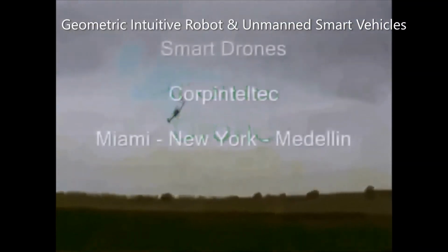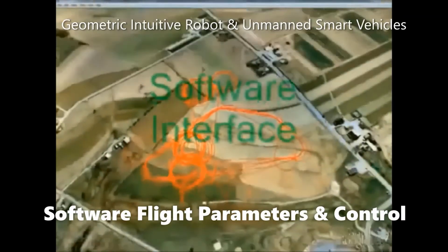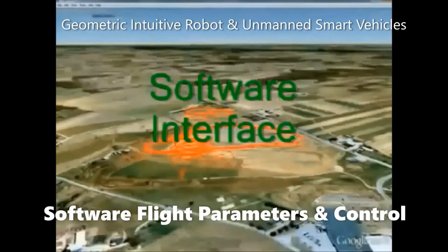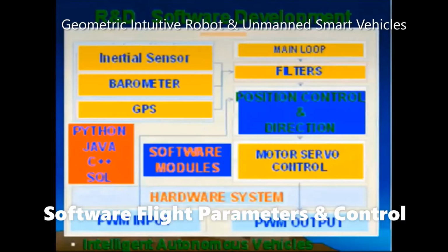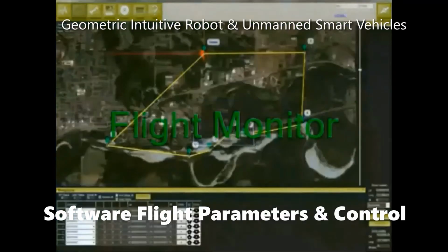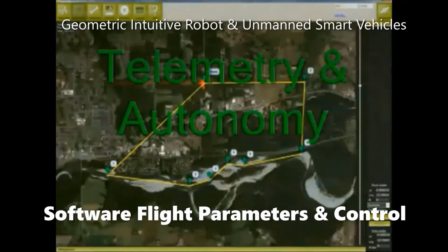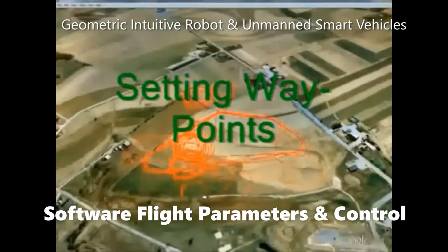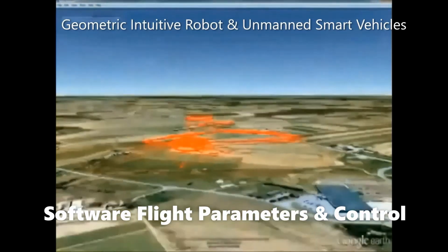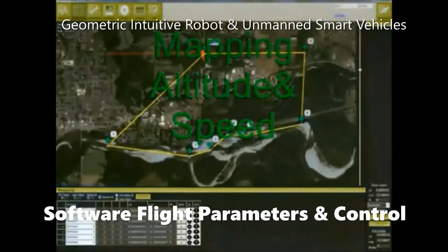Now let's talk about the software interface. There are several software models used to program and to monitor the flight. In this case, we use Mission Planner software. First, set the waypoints on the map. Waypoints include setting altitude, speed, and other actions.